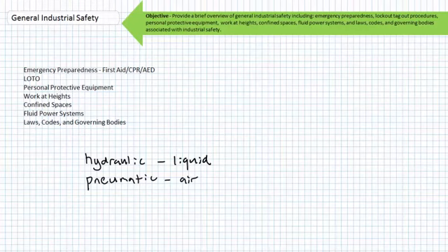Even if high pressure oil isn't injected into your skin, a pool of slippery oil in the wrong spot may be just as deadly. Spilled oil presents an obvious fall hazard as well as an environmental concern that must be responded to immediately. This is doubly so for exotic fluids used in industrial processes presenting a chemical or flammability hazard. Material safety data sheets should accompany all systems and make abundantly clear any special precautions necessary to limit loss of life or prevent injuries. At all times, consider the clearance of fluid power actuators like cylinder rods or mechanical linkages.